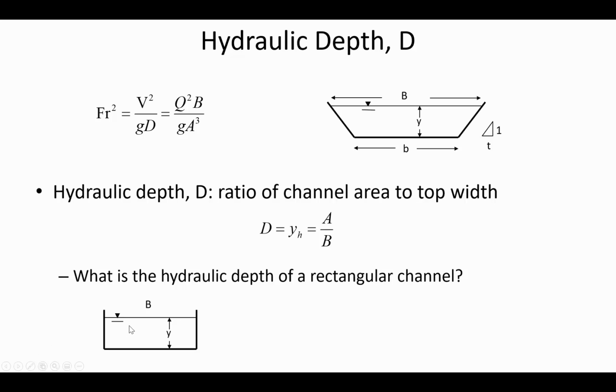Of a rectangular channel, the hydraulic depth is simply the depth itself, because it would be B times Y for the area, and then if you're dividing by B, then all that's left is Y. So the hydraulic depth of a rectangular channel is the depth itself.